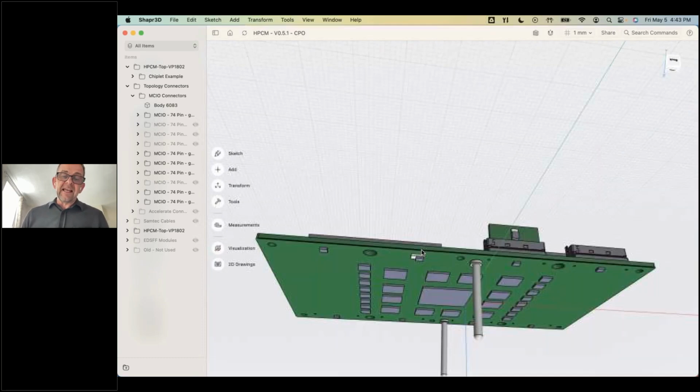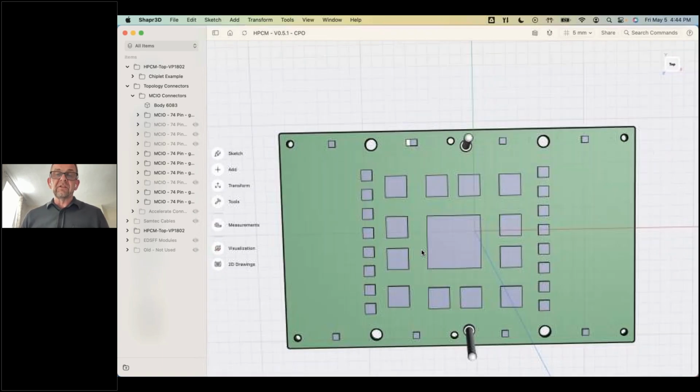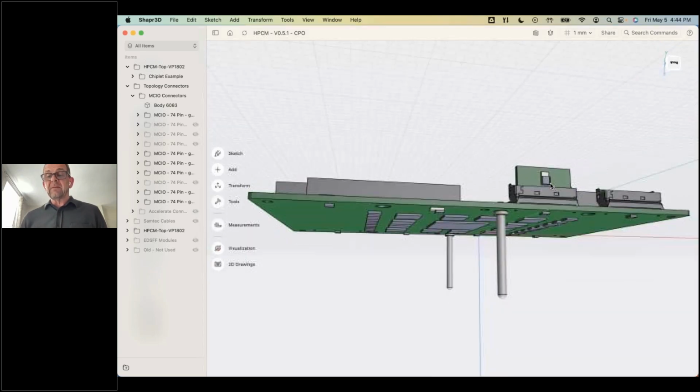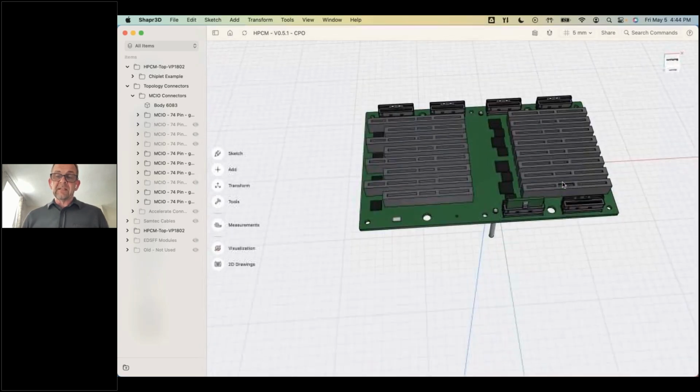So, I mean, this is very cartoony, but the idea here is we can start to introduce optics, and we don't have to go all the way to co-packaged optics, and it might be easier to go to this near packaged optics. And this could be a half a picojoule per bit interface, maybe. And then if you've got picojoule per bit optics, then that's quite a low power optical cable that could go up and down the data center. So that's that. Any questions on that? Again, if you're a photonics expert, you can drill into me now.